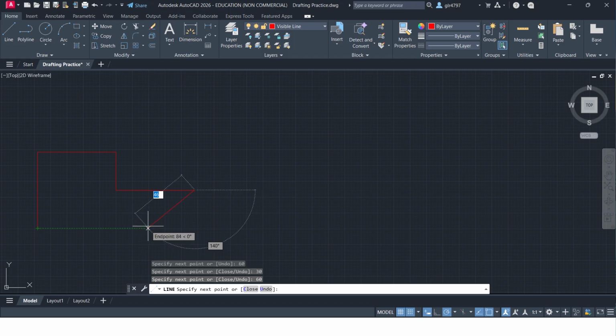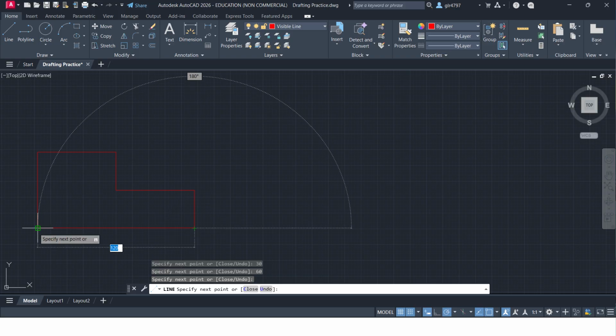And what you're going to do is slowly drag your mouse to the right. And now look at that. It's creating a horizontal guide ray, which eventually should intersect the vertical guide ray. So then you're going to select. Okay, look at that. It now snapped exactly where you needed it to. And then you're going to just close the object, click escape.